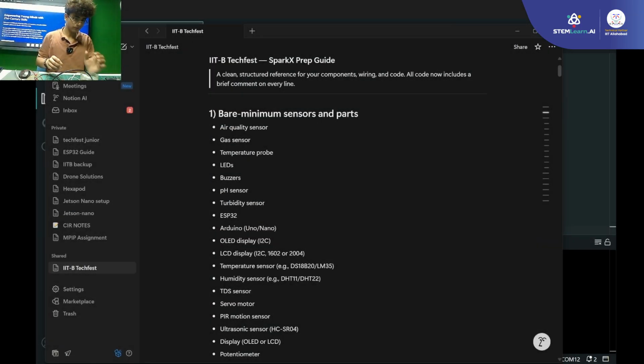So now that we have displayed this thing in serial monitor, we should be able to display it on an LCD display as well. This is an LCD display and it works on a protocol called I2C. The I2C protocol is being used because here there are so many pins. To convert this into just 4 pins, we will use this protocol. To study in detail about it, you will have to search about it. So let's use this.